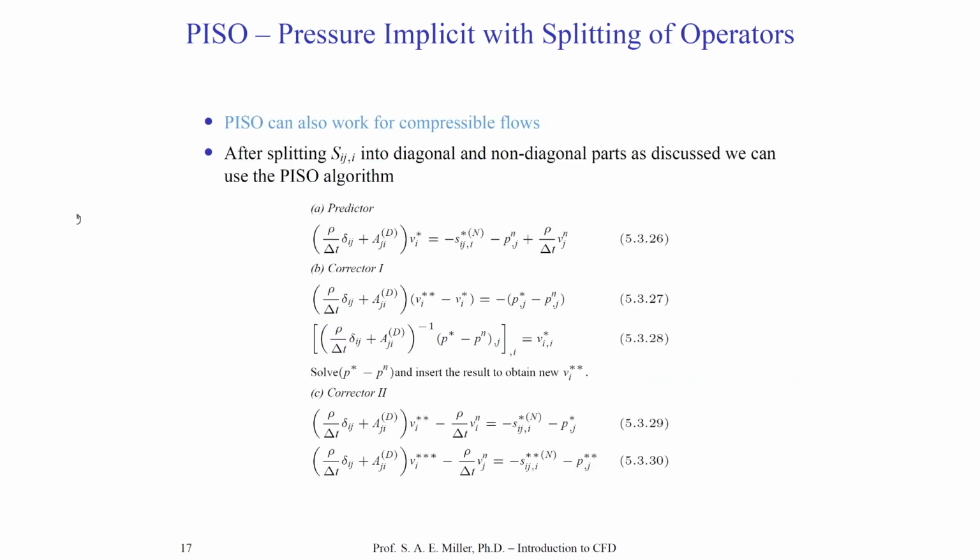Now, that's an incompressible flow and the whole PISO algorithm, which you can, of course, implement when you run the PISO incompressible solver on, say, Fluent or Star or other commercial software codes. You can imagine it's a lot of work to implement these just for the laminar equations, but once again, they can also be implemented and applied to flows with a turbulence model. Now, what if we want to consider a flow which has compressibility, which is perhaps in a general sense seen as a flow with Mach number greater than 0.3?